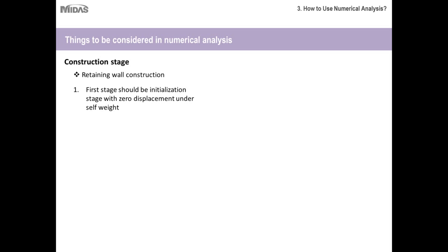This means that the slope exists as it is in the field, and it is stabilized or fully consolidated under its own self weight. So you'll just model the existing soil strata in whatever state it is, and set the displacement after this stage as 0. This means that whatever has happened prior to our construction is our initial condition, and whatever happens thereafter is something we'll monitor.